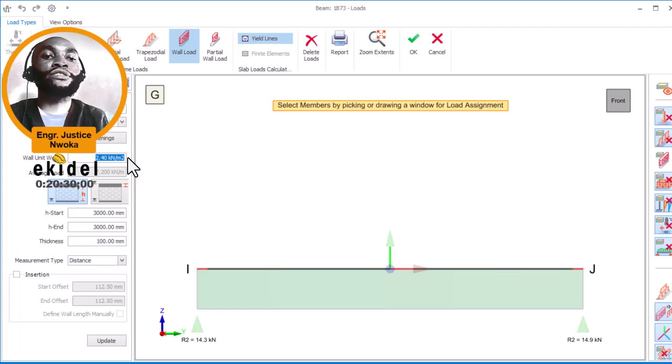You can see it says wall unit weight. We are using a 9 inches block wall, which is the 225 wall. The value for that is 3.47. You can check that out. How we got this is that the weight of one block without plastering is 2.85. Then if you add 0.6 as the plastering weight, you get this value, 3.47. That's fine.